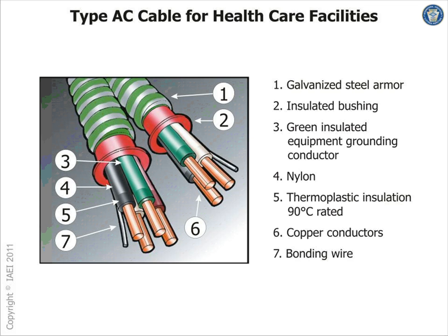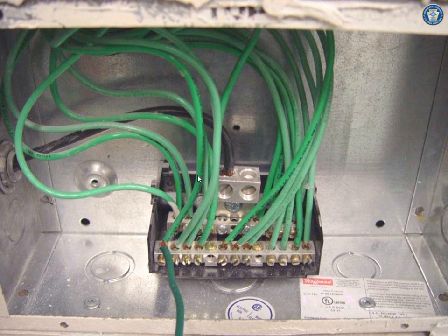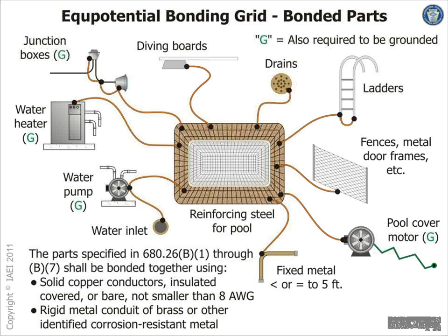It's a redundant insulated grounding conductor. Yes, you pull them all together, but you have to tie them at the equipment. It's not an isolated ground system for data, and even the data guys don't like it.